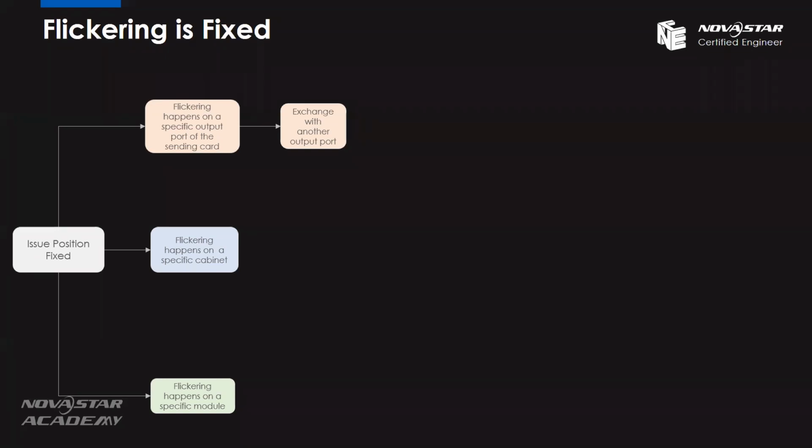Okay, we can exchange port 1 with port 2. If the problem stays on the same old output port, which means after we replace these cables the problem is still on this port loading area, we can confirm it's a sending card output port issue.